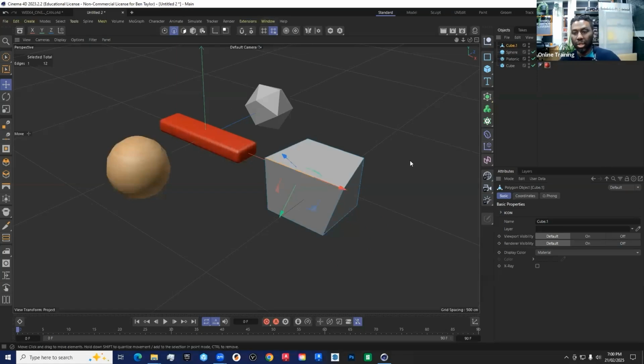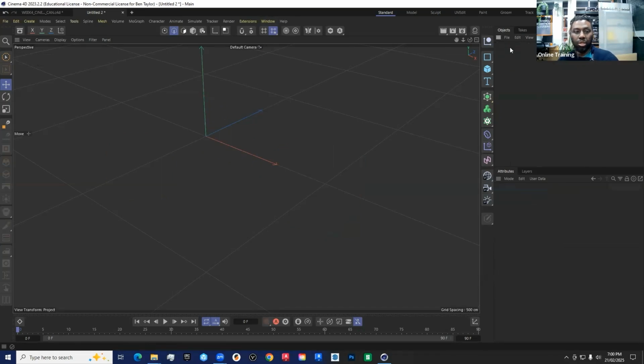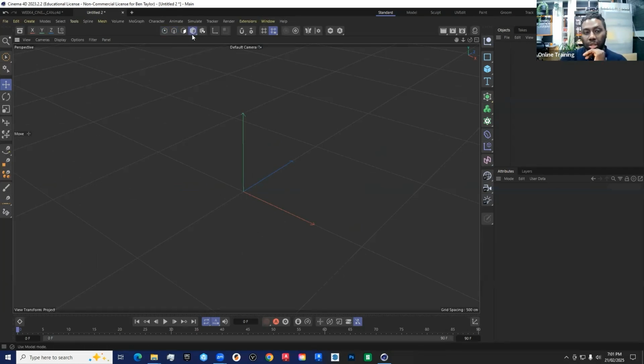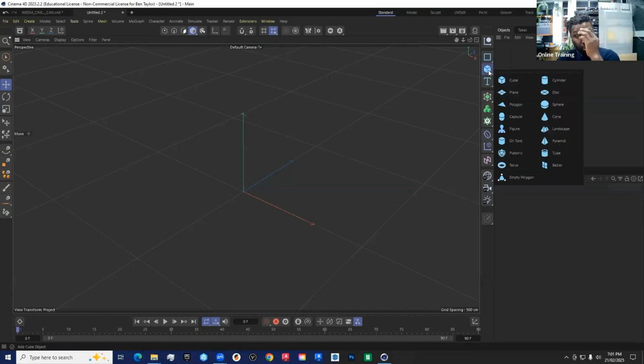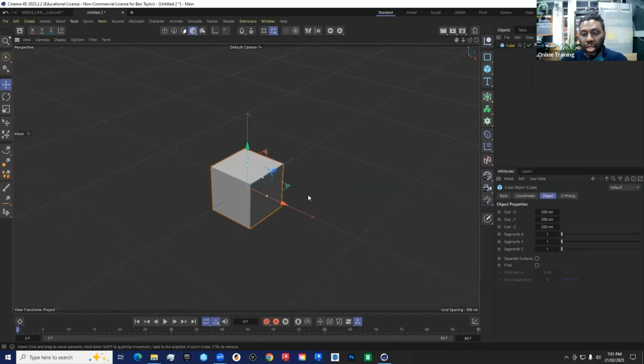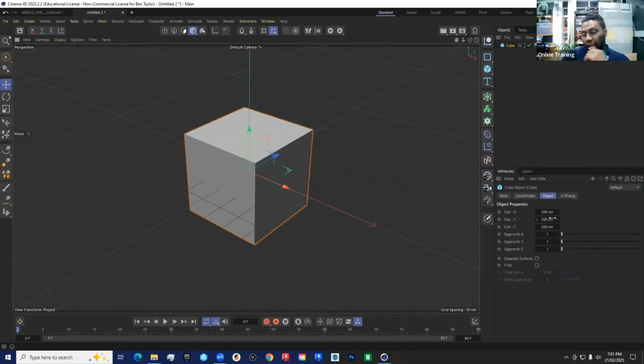Okay, so if I delete the information here, I'll start with creating a cube and just navigating around that. It's a thing that we can all do. You should be on this icon here, our Model icon. If you're not, strange things will happen. If you hold down on the cube icon, it will create a cube, and that cube will be 200 centimeters.